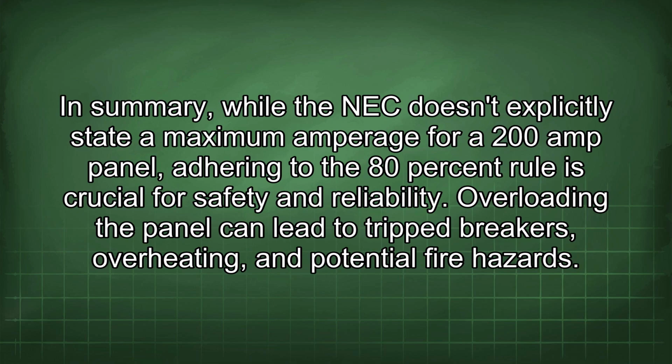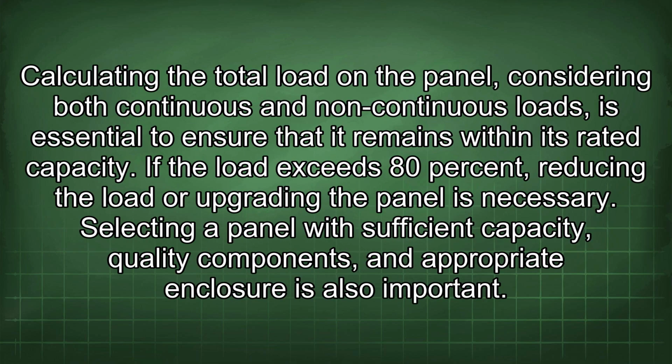In summary, while the NEC doesn't explicitly state a maximum amperage for a 200 amp panel, adhering to the 80% rule is crucial for safety and reliability. Overloading the panel can lead to tripped breakers, overheating, and potential fire hazards. Calculating the total load in a panel, considering both continuous and non-continuous loads, is essential to ensure that it remains within its rated capacity. If the load exceeds 80%, reducing the load or upgrading the panel is necessary.